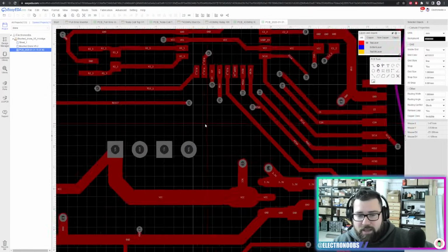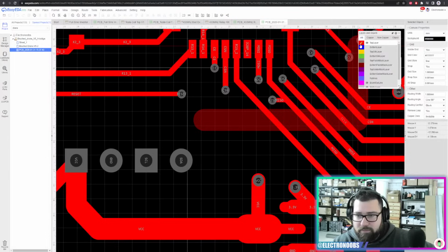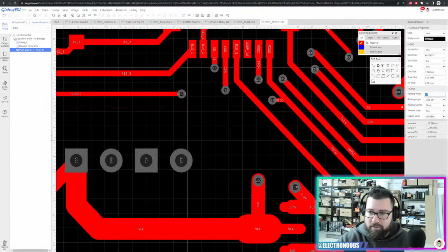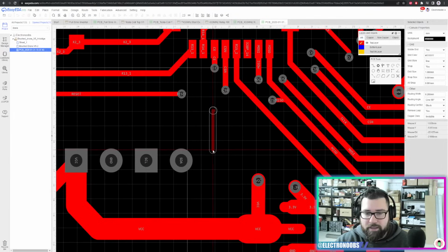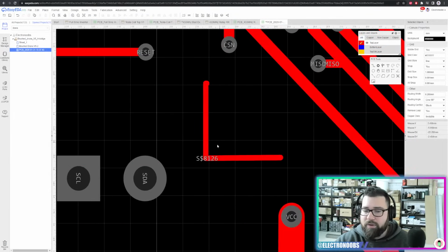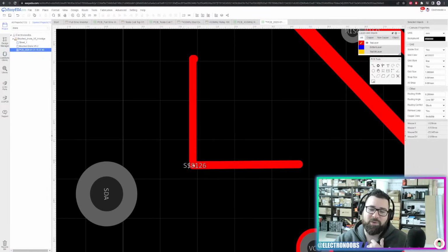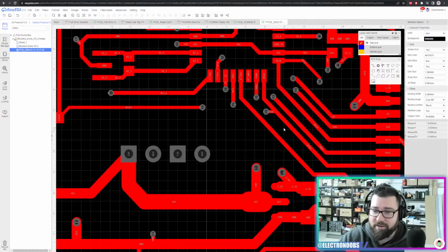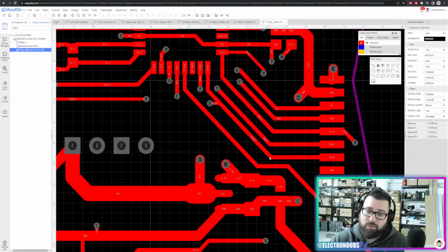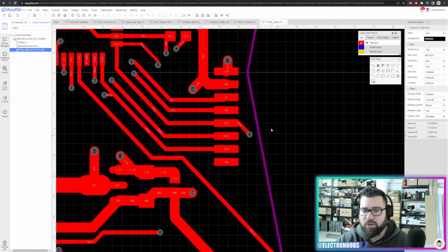So for example, if you make an angle like this, if you make an angle like this, high frequency won't like this angle too much. It's like a car going at high frequency and won't be able to make the curve. So usually it is a lot better to use 45 degrees angles.